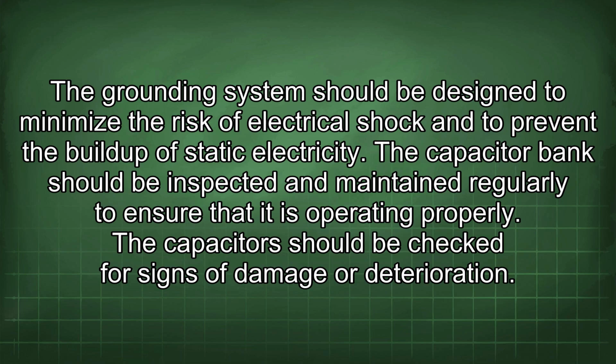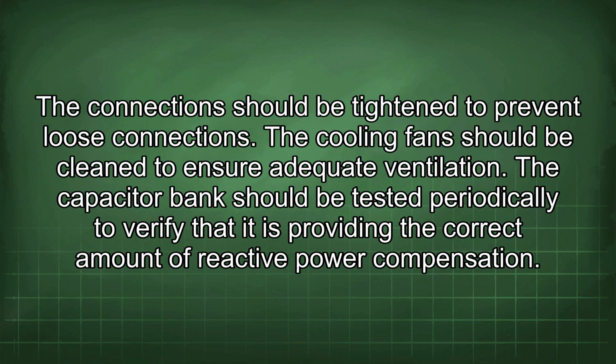The capacitors should be checked for signs of damage or deterioration. The connections should be tightened to prevent loose connections. The cooling fan should be cleaned to ensure adequate ventilation. The capacitor bank should be tested periodically to verify that it is providing the correct amount of reactive power compensation.